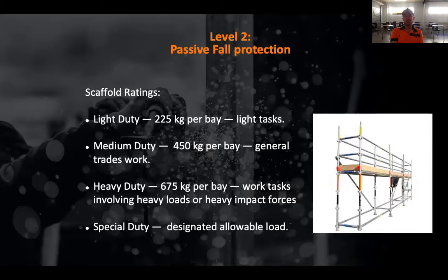Like I said, there's a compliance tag on the stairs before you enter a scaffold. You need to check not only that it's in date, that it's been inspected and compliant, but you also need to check the weight rating of it prior, so you know your limitations for that scaffold.